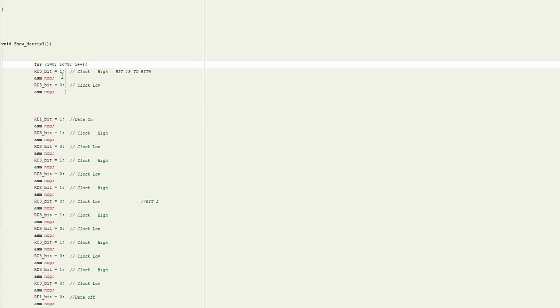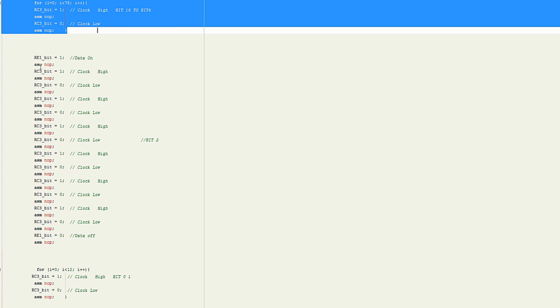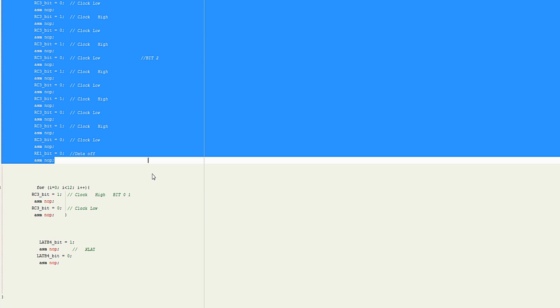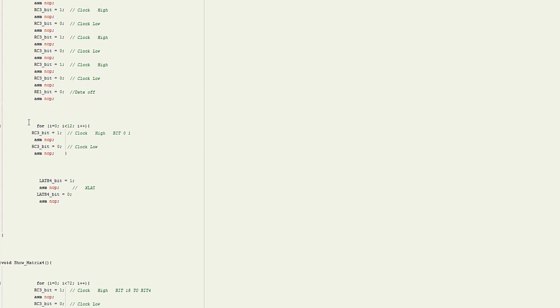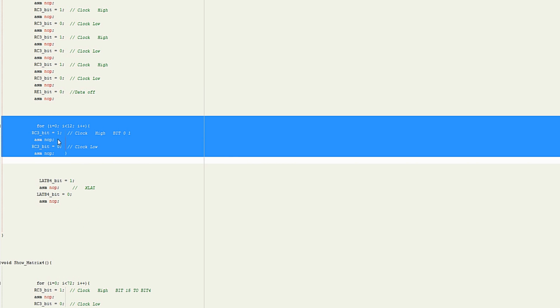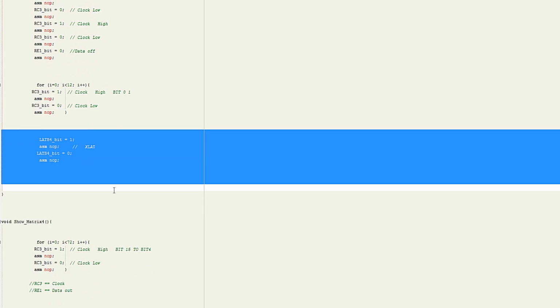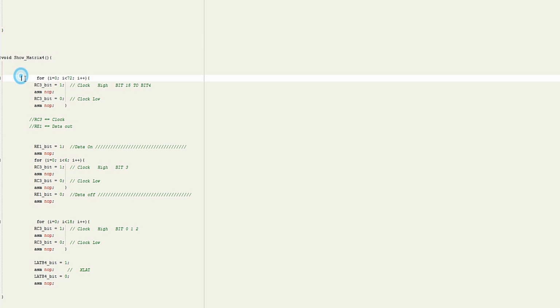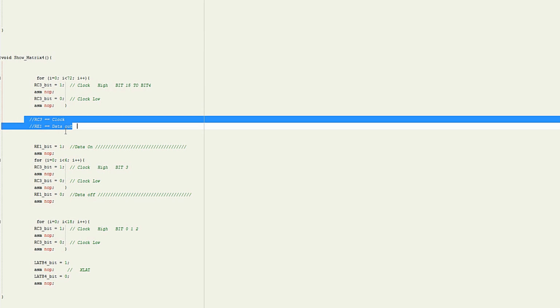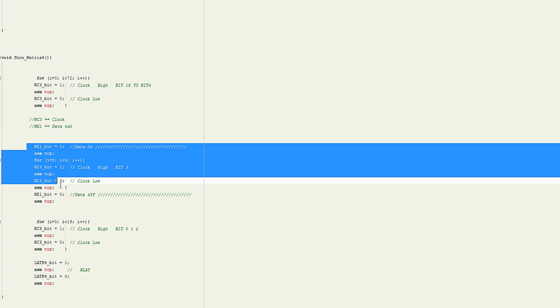and you see there's 78. One bit of data, a bit 2, that's LED 2, down another row, then 2 lots of clock pulses, so 12 clock pulses, that's 2 lots of data for 2 LEDs, so 2 doing nothing, latch, and you can see here I started becoming familiar, so there's 72 clock pulses, just a confirmation that's the clock and that's the data out, and that's the data, just doing it once.